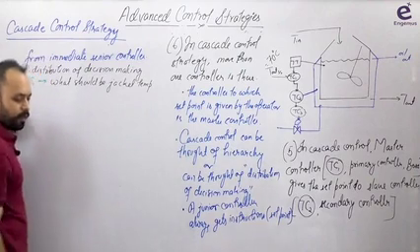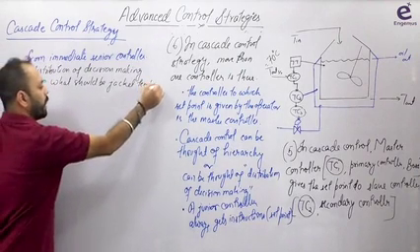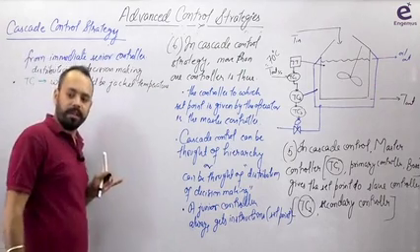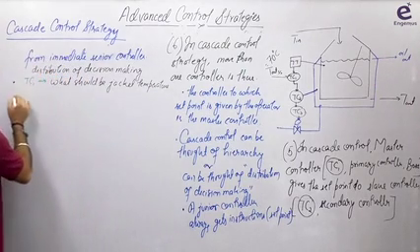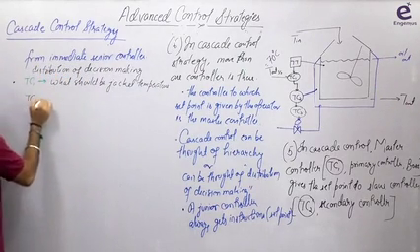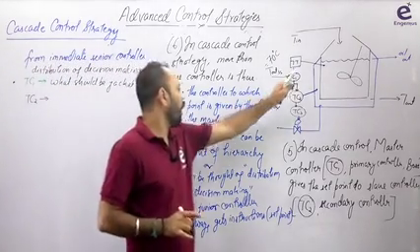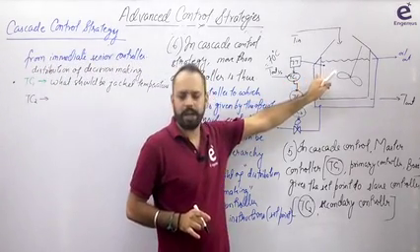That is the decision taken by TC1. What should be jacket temperature to maintain the liquid temperature at 70 degrees Celsius. Now, TC2 is going to receive the instruction that okay, I have to maintain 70 degrees Celsius jacket temperature.